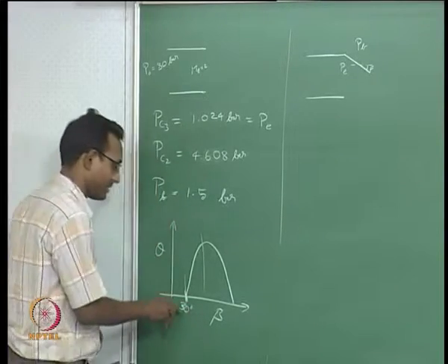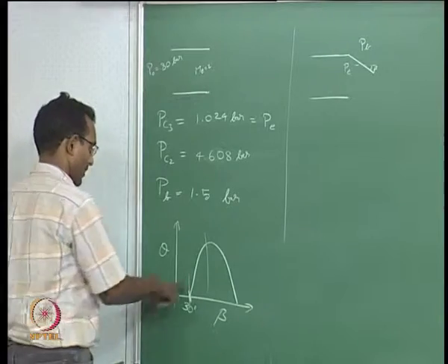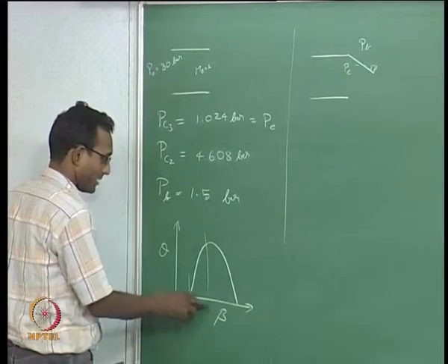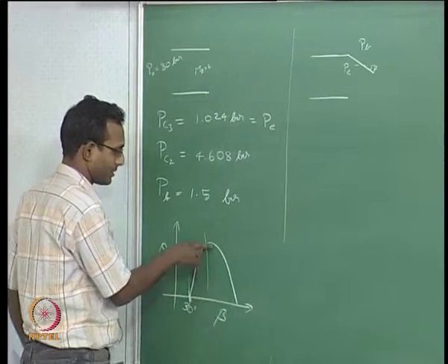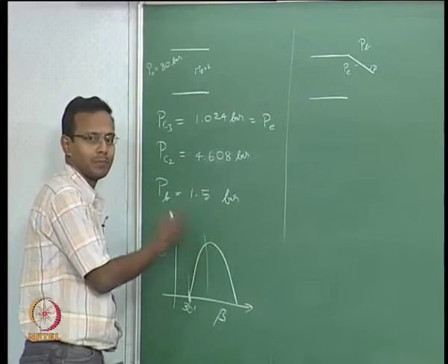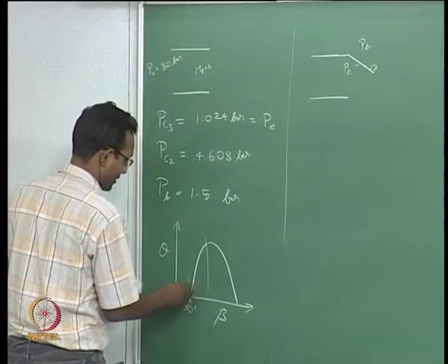How do you know that? That is the sine inverse of 1 by 2, where 2 is our Mach number. That is your Mach angle, and so I want to guess some value inside here. If you go look at the Mach 2 condition, this peak value will be around 63 or something. We won't worry about that. Currently, we will just look at numbers as something in between.